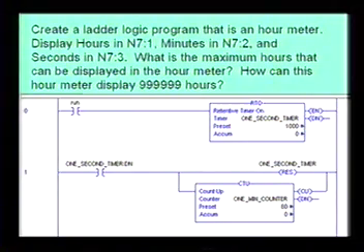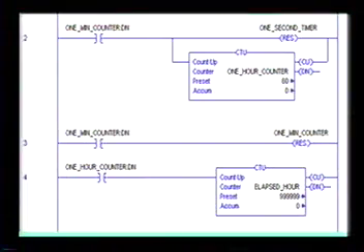Stop your TV, play this in a regular DVD, and then write this code, and then carry on to the next lines and write that code. And you might come up with a dozen different ways to do this, a dozen better ways to do this. This is just one way. It's not tied to the internal clock, so it's not a very accurate way of doing elapsed hours. But for most people in the world, if they know that their motor ran for 4,000 hours, that gives them a heads up that it's time to do some maintenance. Whether it's off a minute or so, I don't think they really care. And if it's real critical, then you need to do something better than this and start using real-time clocks.